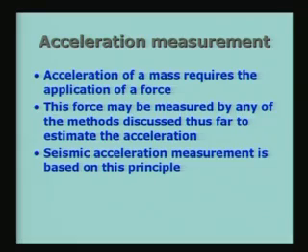For example, seismic acceleration measurement is based on this principle. We subject what is called a seismic mass to an acceleration, and this generates a force. This force is measured by a spring which is going to be displaced because of this force acting on the seismic mass. So, the measurement is actually the displacement of a spring, which is equivalent to a force. This force is equivalent to an acceleration multiplied by the mass. Knowing the mass, I can find out the acceleration. It is a very simple way of doing it.